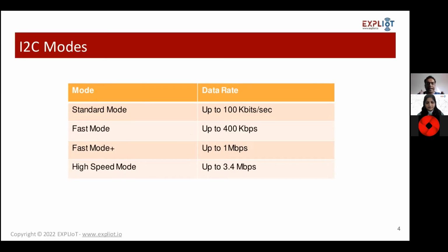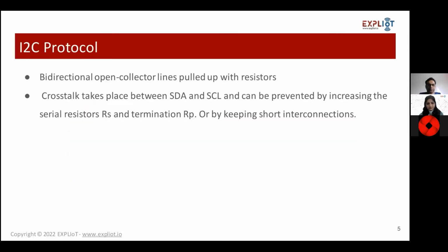Where I'm interested in reliable communication, sending data and wanting to know whether it has reached there or not, I'll certainly follow I2C. Because of the slow communication, it is also much more preferred in scenarios with low power consumption IoT devices. So most of the sensors are based on the I2C protocol.